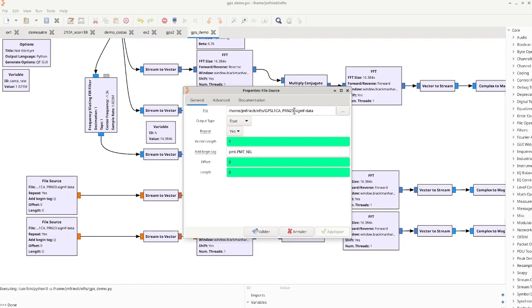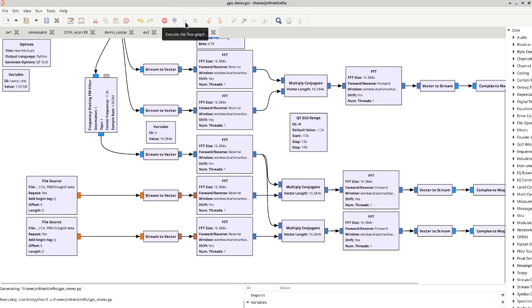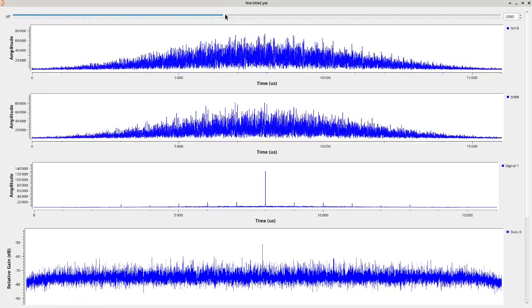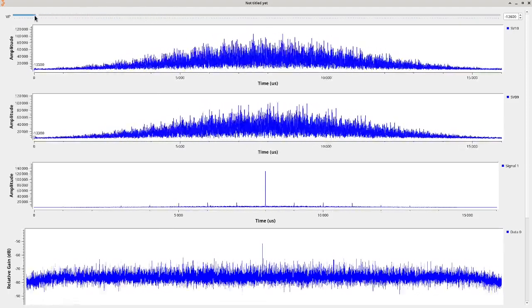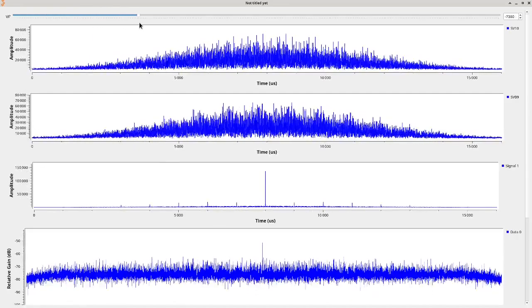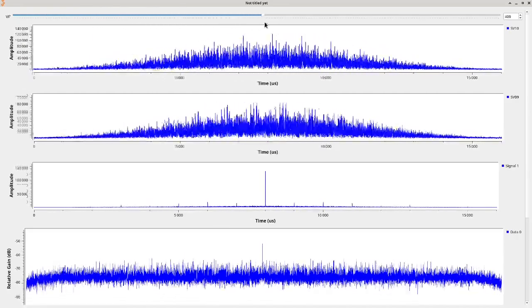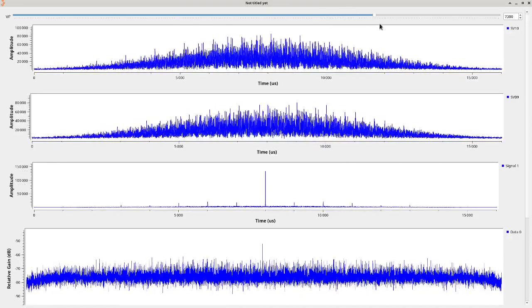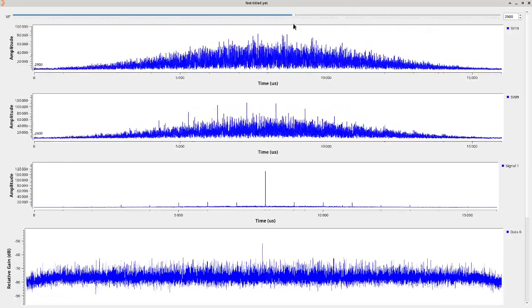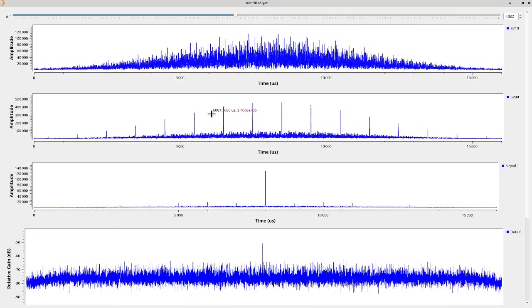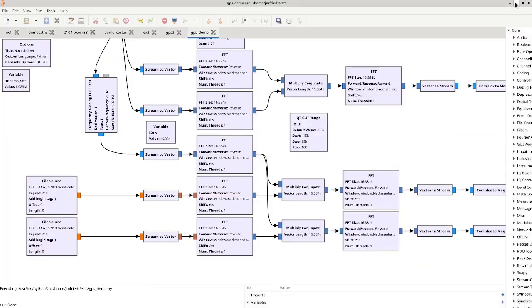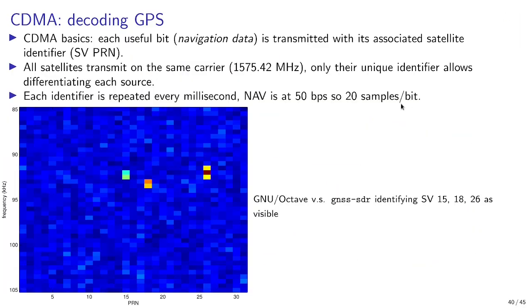If we convert this space vehicle number 23 with space vehicle number 10, we might search for the frequency offset that will allow detecting the signal, but if space vehicle number 10 has not been recorded, the correlation will never accumulate. And indeed, on the top chart, whatever the frequency offset that we search for, we are unable to detect the signal, whereas the second chart from top will exhibit the correlation when the frequency is compensated for. So this summarizes the complete steps needed for acquisition of the GPS signal.